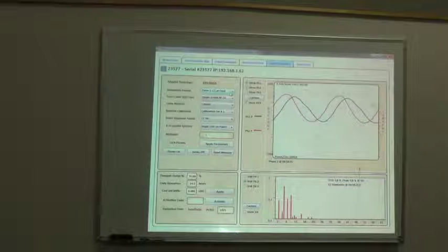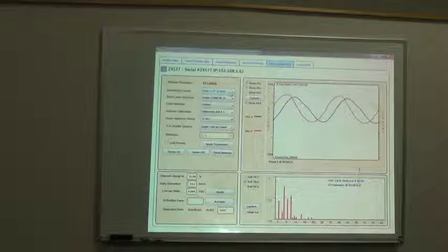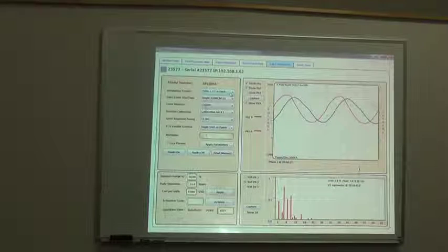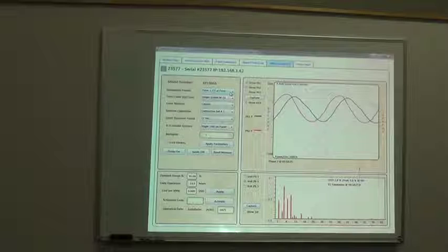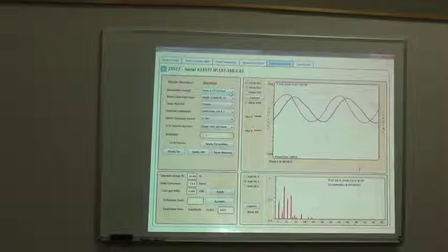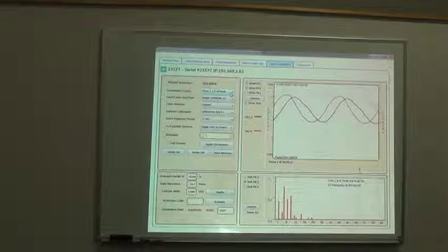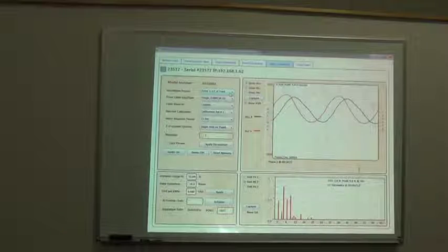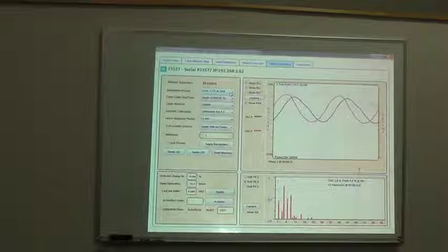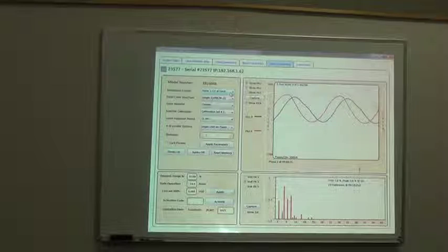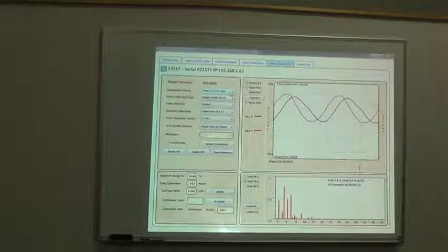You know what I'm saying? Because if the CT is on the feed, then the current that goes through the capacitor itself is also being added. And by the big load shutting off, you basically are putting the unit into a leading power factor, and it takes a bit of time for it to recover from it. If in that time frame the big load turns back on again, now you have a cycle you never get out of.